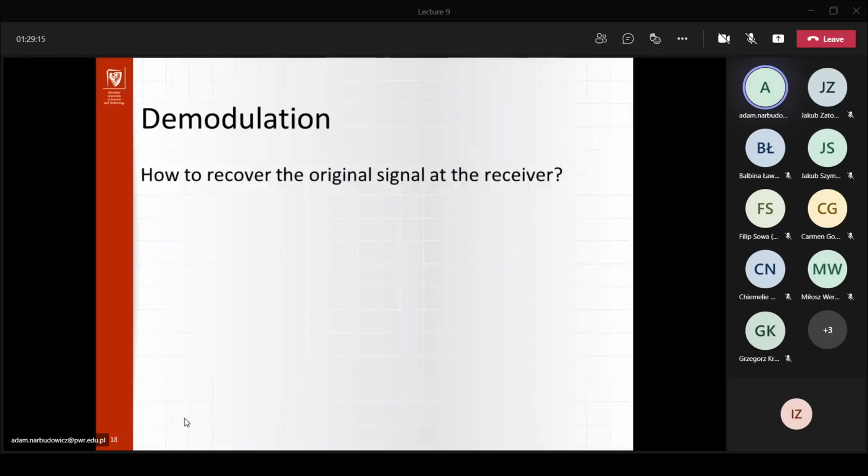So this could of course work up to a certain frequency. However, the problem is that it's not very easy to do if we're thinking about high frequency signals, right? So generally, we want to move back from the high frequency to the baseband frequency, and only then at lower frequency can we effectively use diodes.